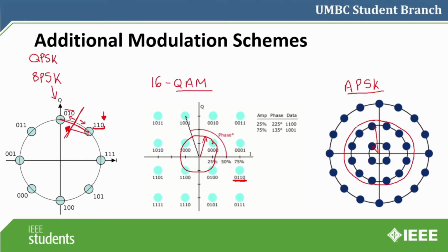So it just depends on what system you're working with and which system you need. And a lot of modern systems like 5G will start with a lower data rate like QPSK, and then once they've measured the noise in the system, will swap to higher modulation schemes to get higher data rates, but still keep the number of errors down.